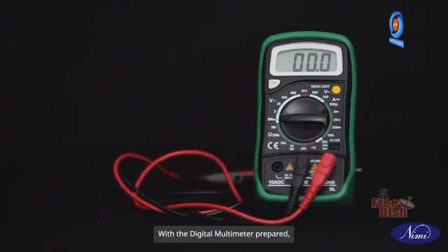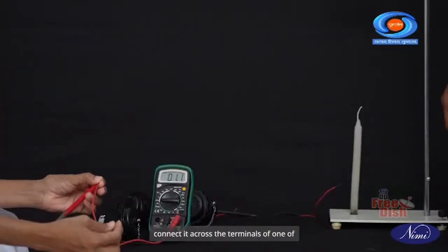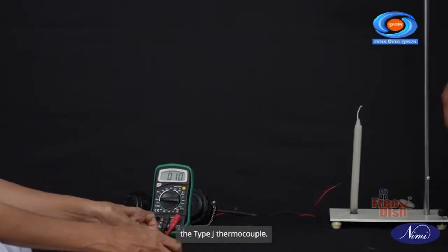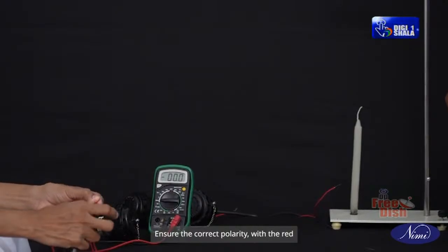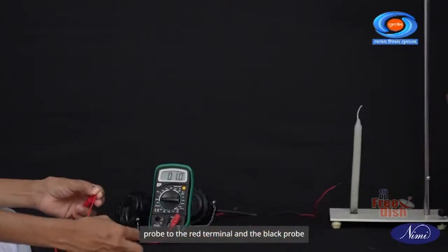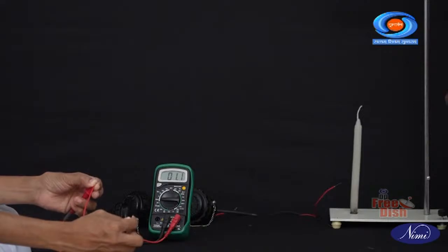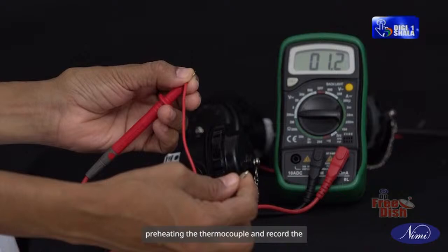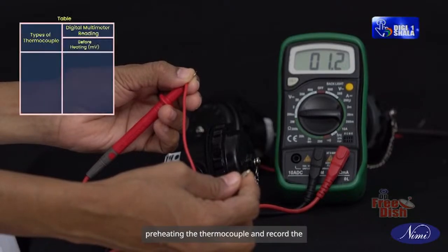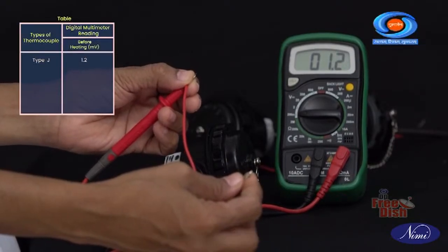With the digital multimeter prepared, connect it across the terminals of one of the type J thermocouple. Ensure correct polarity with the red probe to the red terminal and the black probe to the white terminal. Measure the DC millivolts reading before preheating the thermocouple and record the value in the designated table.